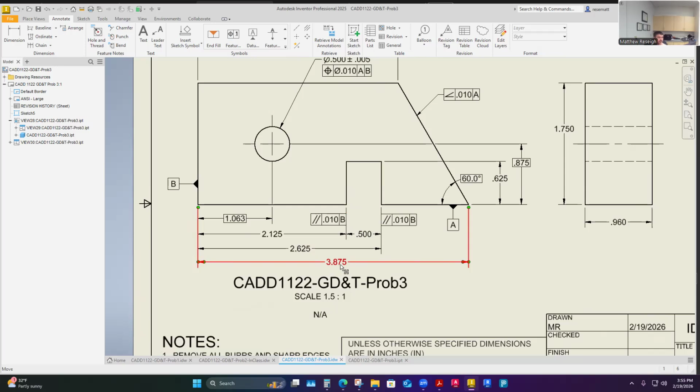Maybe they could all become basic. And I have to maintain that this is half inch, and I have to maintain that these are parallel to this tolerance zone and that they pull from B. And hopefully the tolerance of this will allow that all to happen. But that's where I can wonder a little bit about these relationships of these three dimensions, because I do feel like I'm definitely going to make this one a basic.